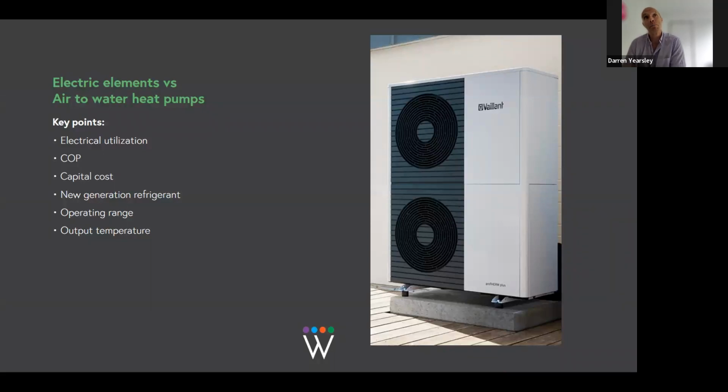And these appliances are very robust. So they will operate right down to about -15. So the COP of the appliance falls when you get into that very, very low temperature, but it still operates all the way down to those sort of levels. So typically, if you've got an outdoor air temperature of around 7 degrees, which is normally the benchmark, if it's producing hot water at 65 degrees, then the COP is 3.1 to 1. So 1 kilowatt in, 3.1 kilowatts of hot water out.